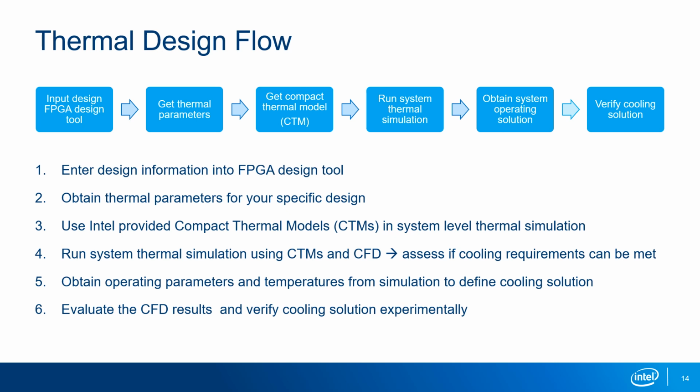We offer one compact thermal model per package. Then the Power Thermal Calculator allows a generic compact thermal model to be used in such a way that it's specific to your design. The thermal simulation is done using a computational fluid dynamics software cooling package like FloTHERM, IcePak, or Sigrity ET.